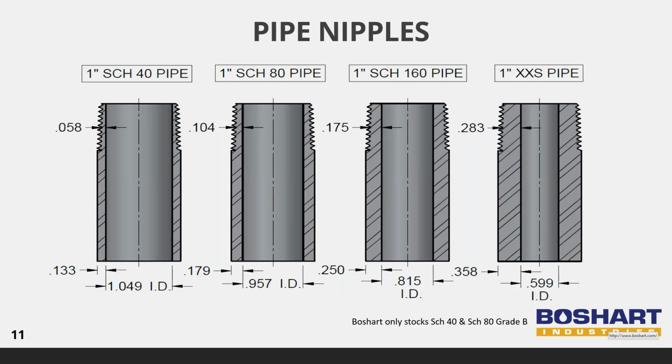The allowable working pressures for pipe nipples are derived from ASME B31.3 Process Piping Code. Considerations were taken into account for the wall thickness material removed by threading. Each component must be checked to verify its suitability for the system. The amount of wall thickness lost due to threading an NPT thread on Schedule 40 pipe can be up to 50%. As operating temperature increases, a heavier schedule pipe nipple may be needed to meet the system design requirements.